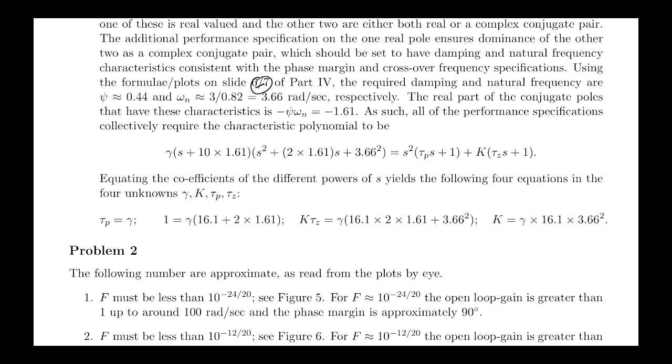You've translated your closed loop specifications, originally expressed in terms of desired phase margin, desired crossover frequency, and where you want the third pole to be relative to the 2 dominant ones, right? That tells us what the characteristic polynomial should look like, right? And this is what the characteristic polynomial looks like for the compensator and plant that we have, right? So then you just have to match coefficients to figure out what the parameters are.